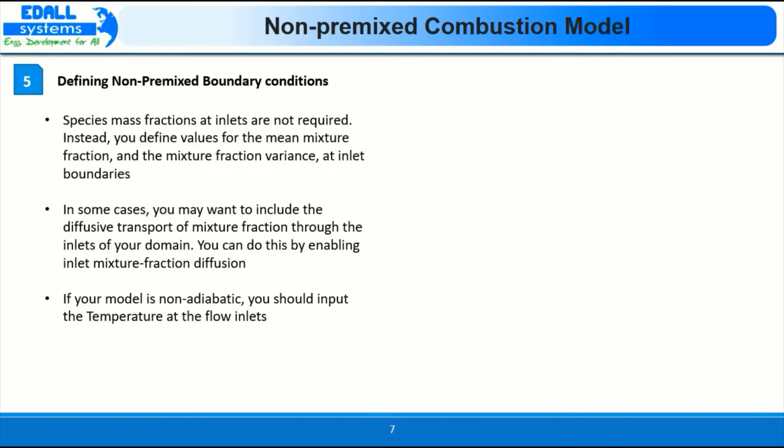We have to specify this at our inlet boundaries, and it is very necessary to define because these are the 2 terms which will be calculated along with other governing equations. In some cases there will be a diffusion problem also, so even that option is present in this model, then we can use inlet mixture fraction diffusion.